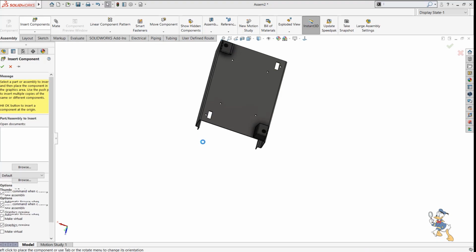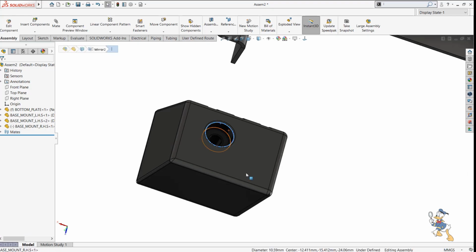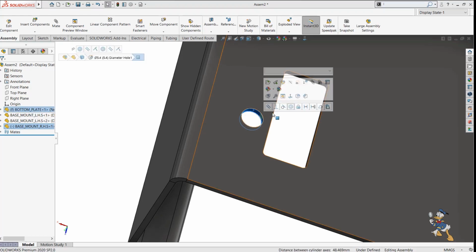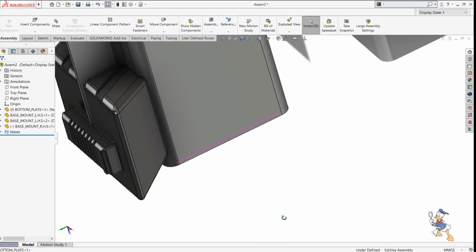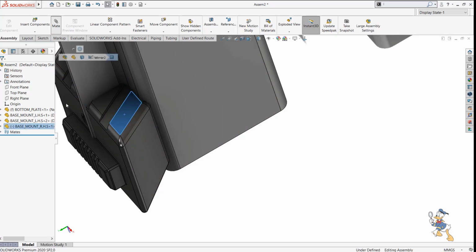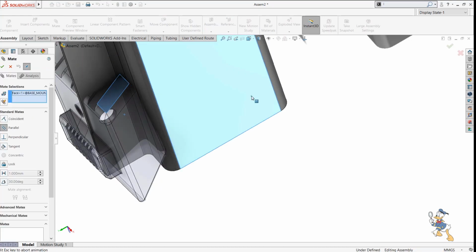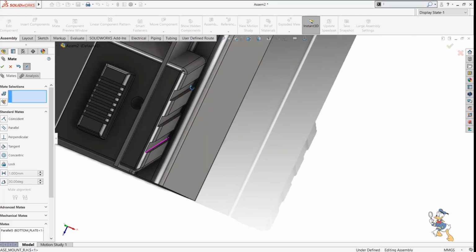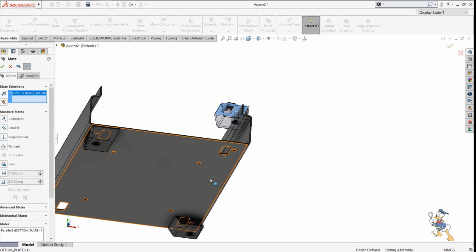So now we just need to provide some more material to the assembly and place some other kind of base mount which is required for these holes. So I just need to place it over here by using a concentric mate, and then I just need to make it parallel to this face. So I just need to select this face, select the parallel feature, and provide the face. As it is opposite, I just need to check opposite, and then I need to make it possible by selecting the coincident face value. So yeah, this is available for us.